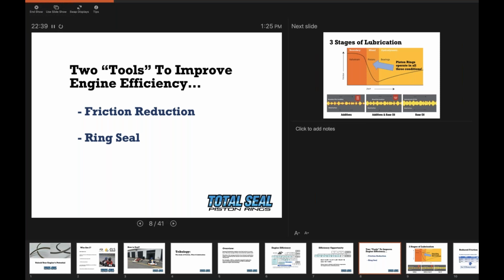In fact, most Formula One engine development is all done on a single cylinder engine, because a V8 essentially is 8 single cylinder engines, and if it's a common plenum and manifold, that's what ties it together. If you look at an individual runner engine, there's not as much crosstalk, because they're all 8 individual cylinder engines with individual runners.